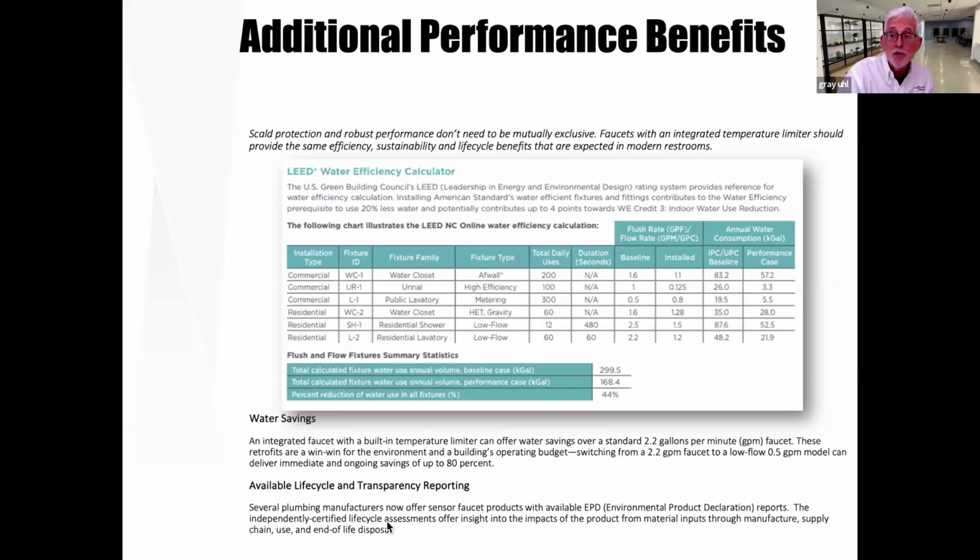You just reminded me of something else that's also a win. If we have an individual thermostatic unit in each faucet, one of the challenges we all have is that as the flow rate comes down, and this is true in showers too, it takes longer to get rid of all the cold water so that the warm water shows up and you get tempered, comfortable water. If you have a central mixing valve, you've expanded the length of time it takes, especially at the lower flow rates, to empty out all the cold water and get the tempered water delivered. You get faster response with an individual unit.